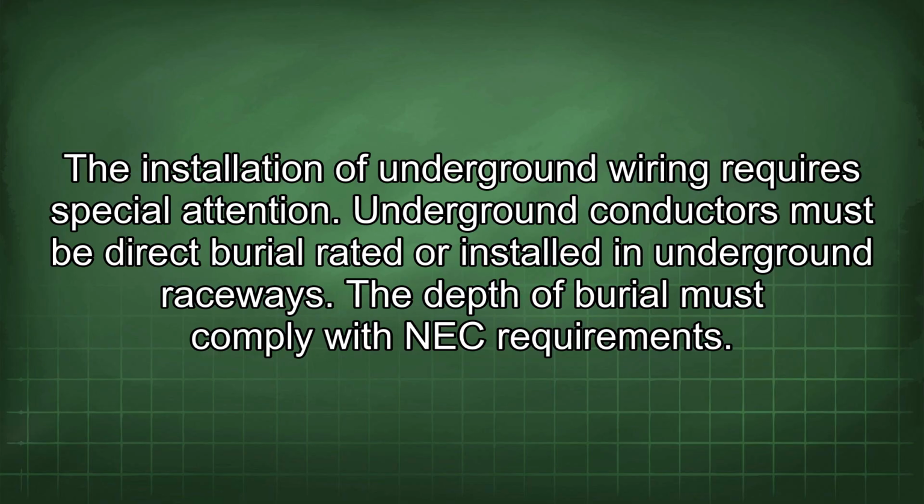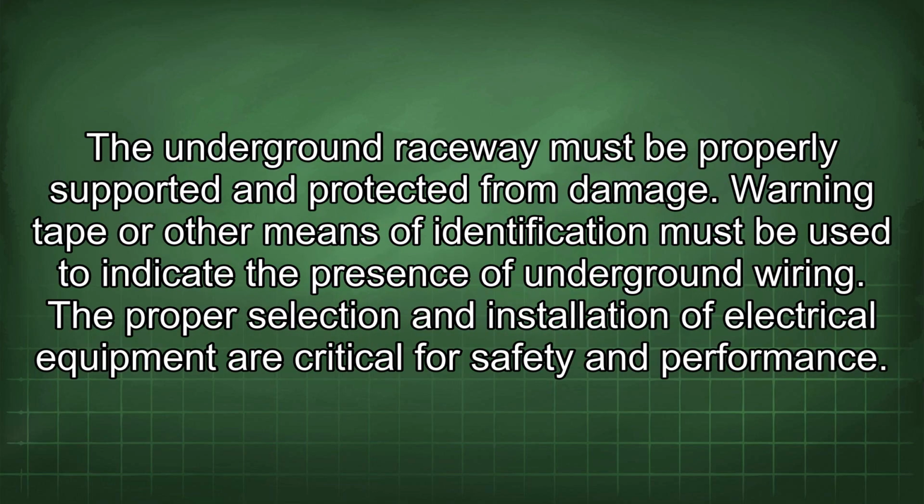The installation of underground wiring requires special attention. Underground conductors must be direct burial rated or installed in underground raceways. Depth of burial must comply with NEC requirements. The underground raceway must be properly supported and protected from damage. Warning tape or other means of identification must be used to indicate the presence of underground wiring.